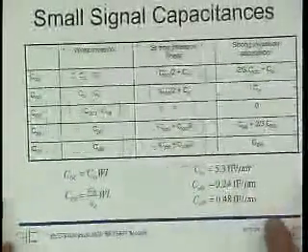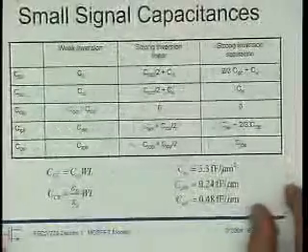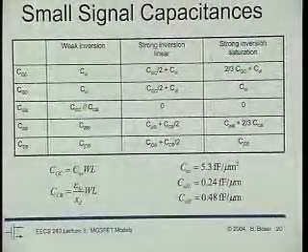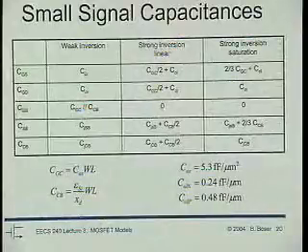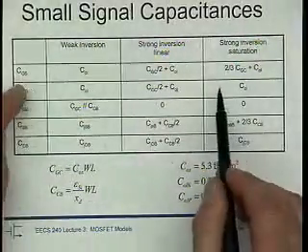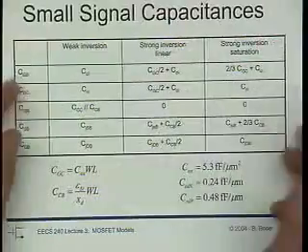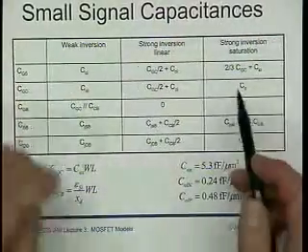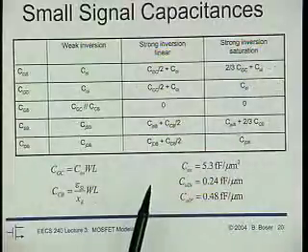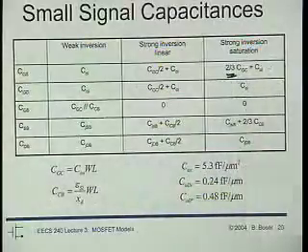Okay. Then this here is something where your undergraduate textbook says a lot. That is, how do we calculate the capacitance between any of these two terminals. Now, there are just a couple of points that I want to mention. So first of all, CGS, when we are in saturation, is going to be 2/3 CG plus the overlap capacitance. So there's 2/3 and so on. You've seen that.